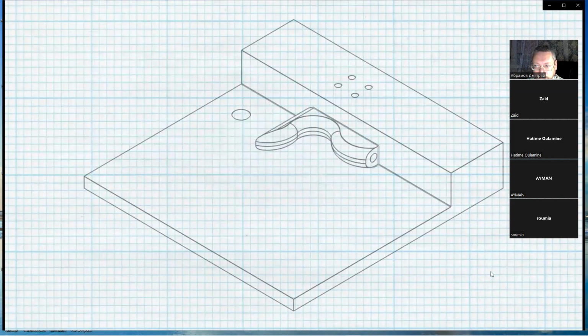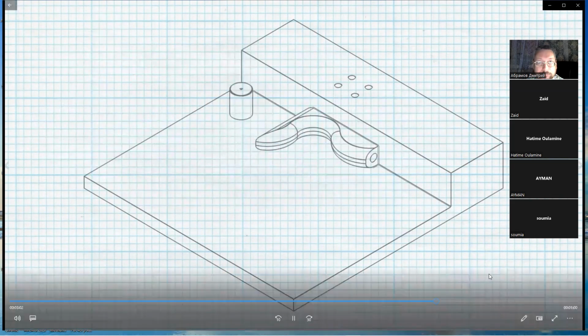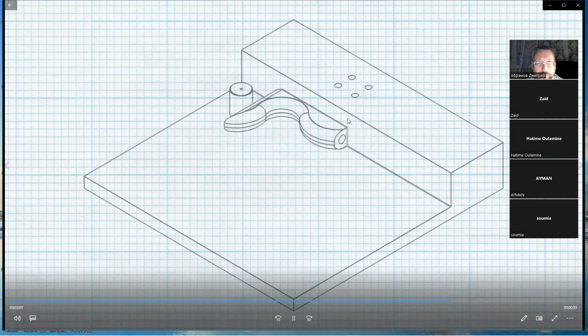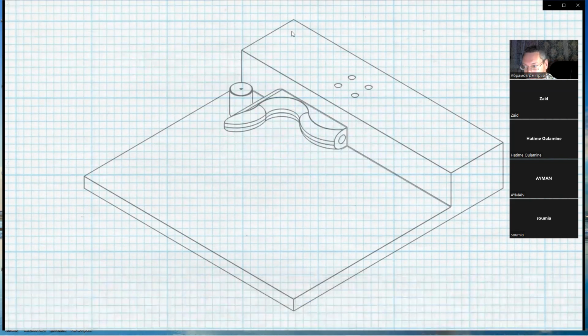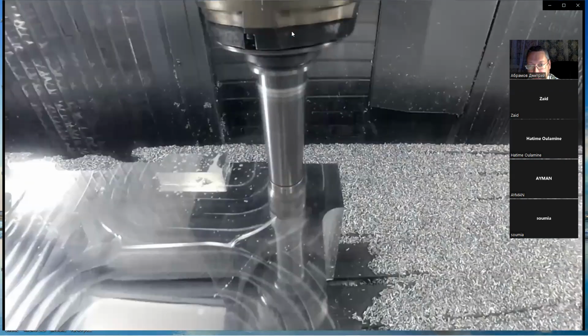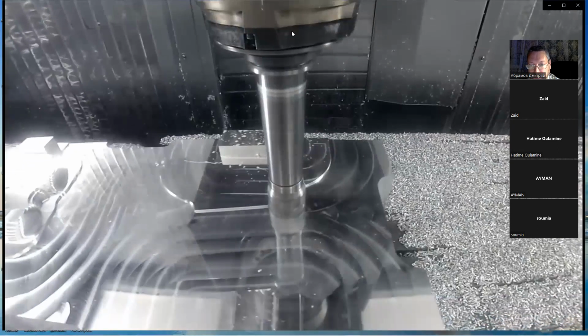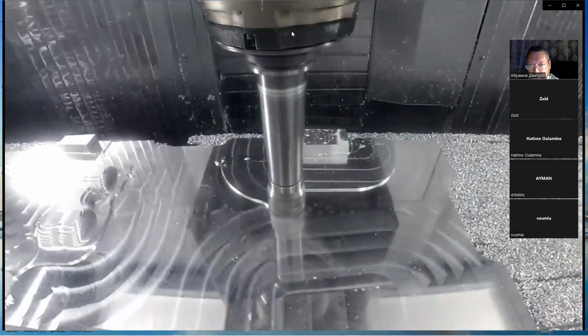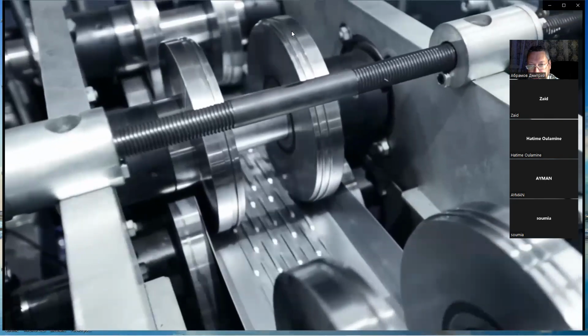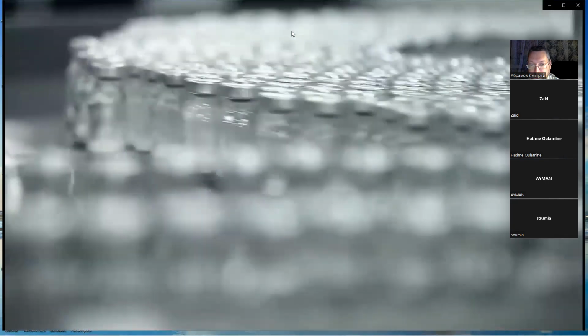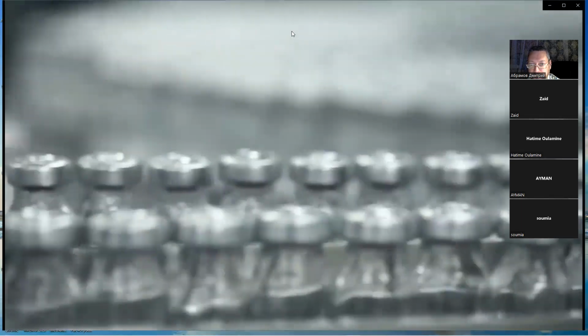These include a support base, which usually restricts downward motion, pitch, and roll, locating pins, which restrict left, right, front, and back translation, and yaw rotation, and toggle clamps, which limit the final degree of freedom, upwards motion. Whether designing fixtures for machining or welding, drill jigs, or any other type of work-holding assembly, remember that the more effectively all 12 degrees of freedom can be restricted, the more reproducible your part can be.